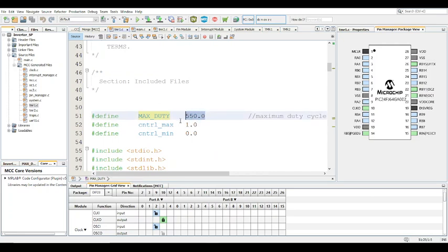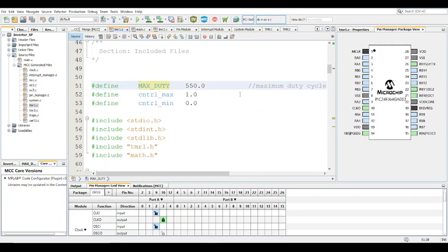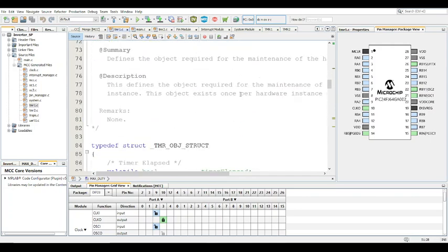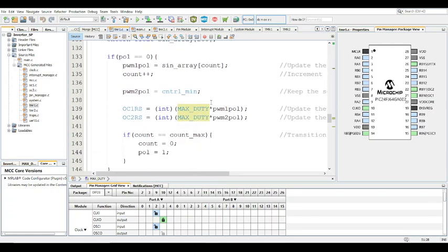But one thing I found is you actually don't want to use the maximum. You want to go below that, to about 500, 600, all depending. I found 550 in this particular example. I'll show you why in just a minute, but 550 is a good number for the max duty, even though the theoretical max is 799, 800. 550 just works fine as well.